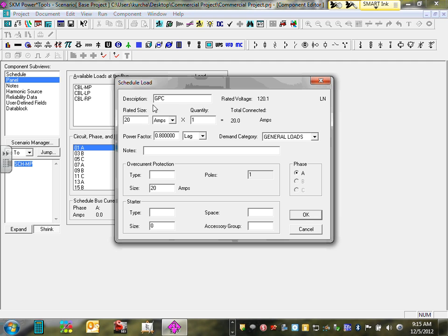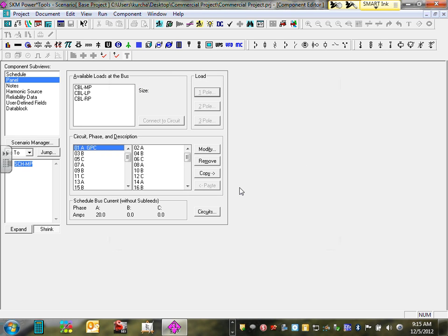Everybody got that one, guys? So I have GPC 20 amp, leave all the default, general load, single phase, 20 amp size, and bam, that's it. Cool? And okay, so now I have a GPC. I build my schedule. I'm building my schedule. Can you give a thumbs up, Chad? We did that first one. Let's go do the second one.